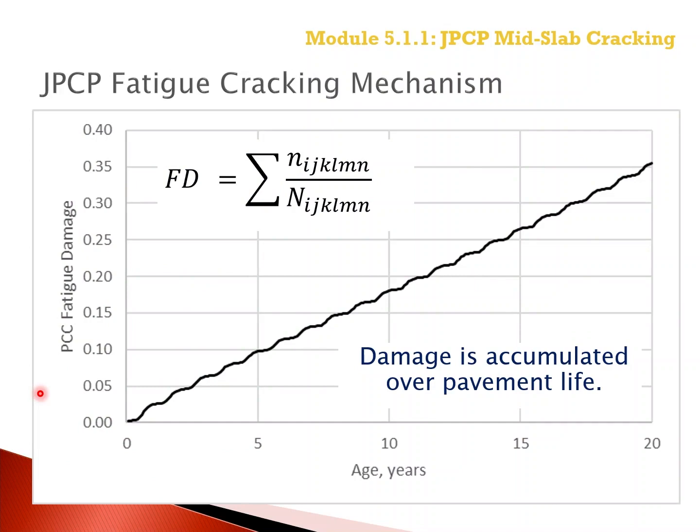In summary, the fatigue damage is accumulated through the design period, considering all of the variables listed and noted on the previous slide. The fatigue damage for top-down and bottom-up fatigue cracks are listed in the output report, which is graphically illustrated in the figure displayed on this slide.